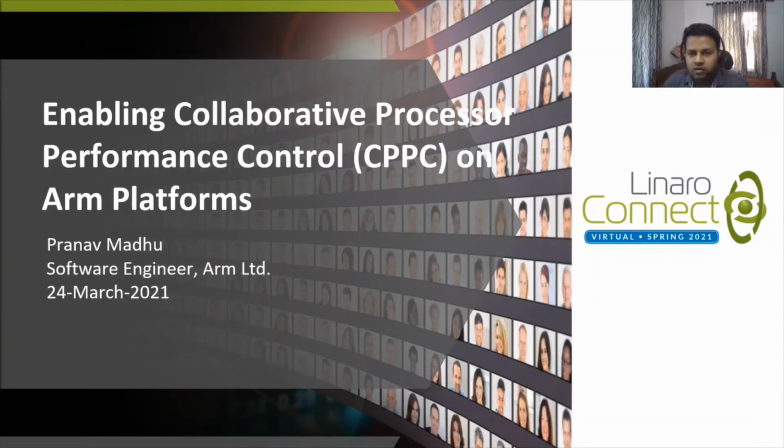Welcome everyone. This is a discussion on collaborative processor performance control, or CPPC, as applied to ARM platform. CPPC is a mechanism for the OS to collaborate with platform firmware to manage the performance of a processor. This discussion focuses on ARM v8.4 system onwards, which has the architected AMU counters.